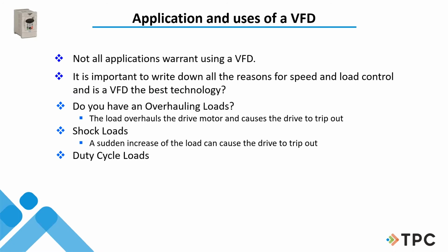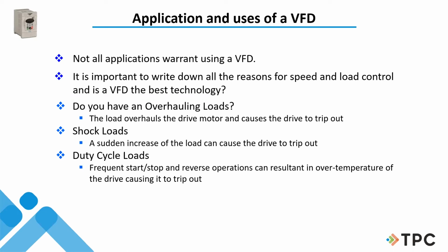Duty cycles, stopping and starting. A lot of times that happens in production modes. Things that get stopped and started, stopped and started. Remember that every time the motor starts up, I get an inrush of current that's going to heat the motor up. It gets turned off right away, then the fan stops running. So if I have frequent stops and starts, sometimes it's just as easy as having an additional cooling fan on the back end of that motor to keep the motor cool.